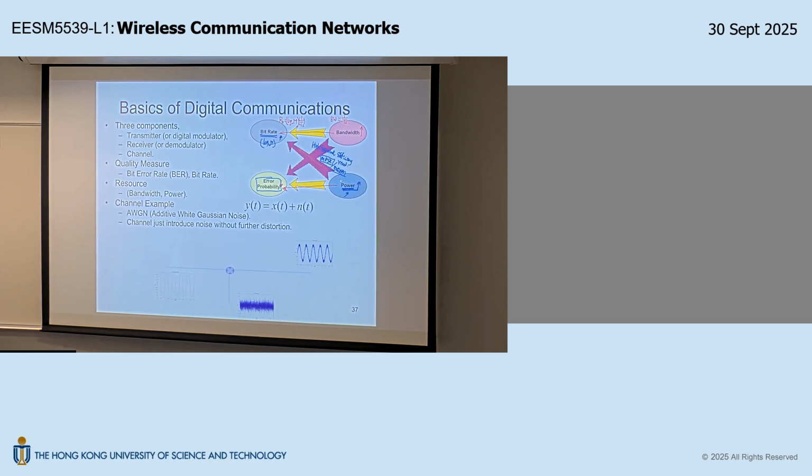Now, just sidetrack a little bit. There is one exception where you may like to use 16 PSK instead of 16 QAM. This is to consider some practical constraint. In a typical transmitter data path, you have a baseband, which is doing the M-ary modulation. So these are the transmitter symbols. And then you will have a power amplifier, then to the antenna, okay?